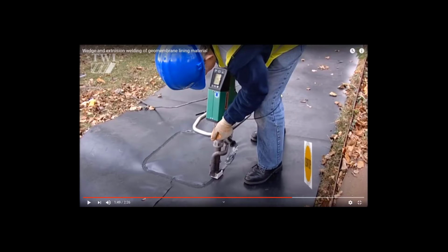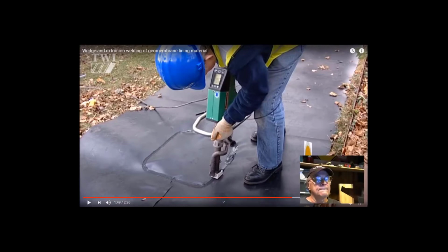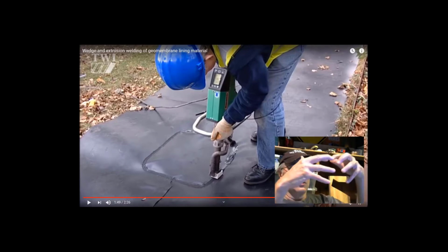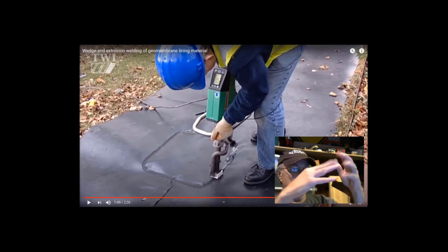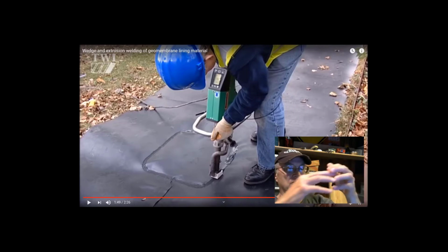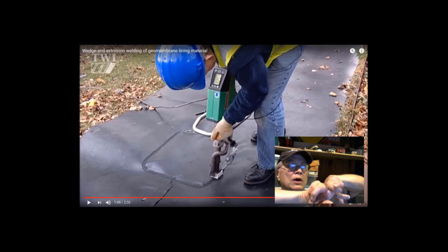But in any case, the question is, how do you weld polymers? And the way it works, I think I'll make this a little bigger. Imagine my fingers being polymer chains, and I get up beyond the glass transition temperature and beyond the crystal melting transition temperature, and so now I have motion. I have real translational motion of these things, and one can come around and loop like that and make an entanglement.